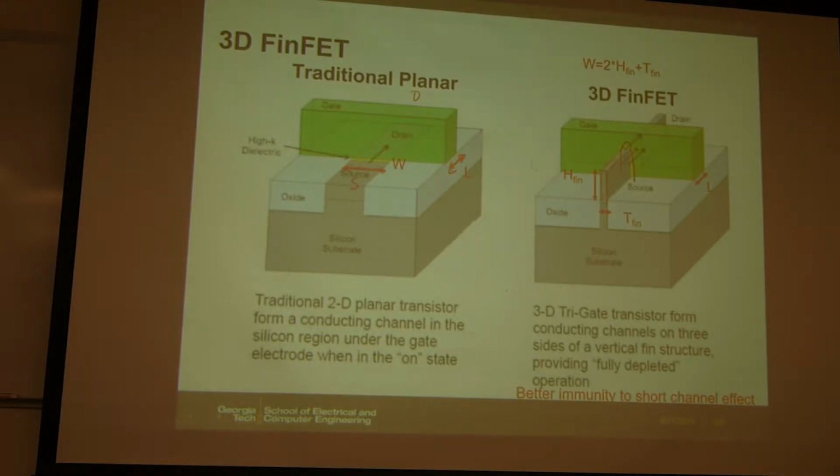So in this FinFET, of course this is still your L, but my question is, what is the W in this case? What is the W in this FinFET? It's written there. Because you look at the gate to the channel, so this is the contact area between the gate and the channel. So you have two sides of this fin. That means 2 times the height of the fin, this H fin.